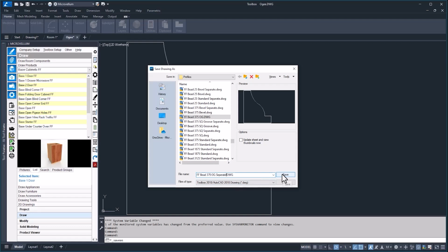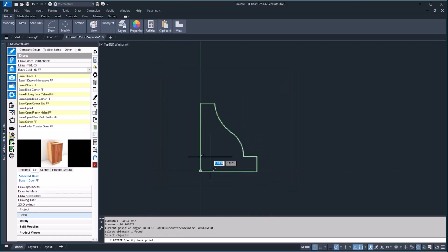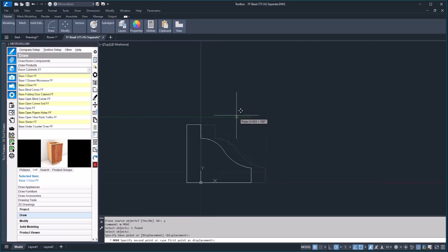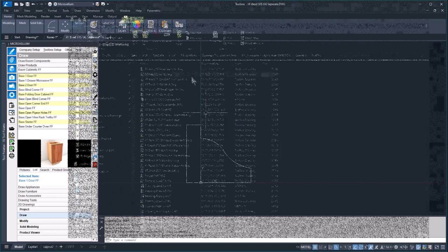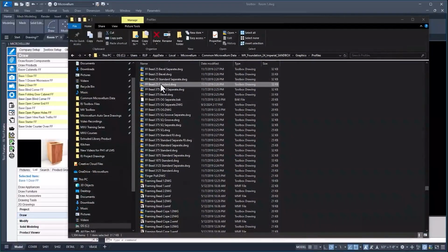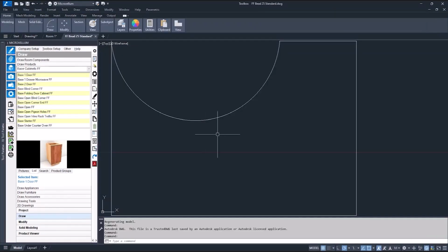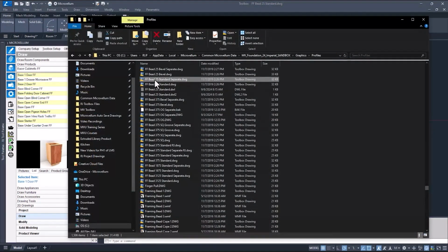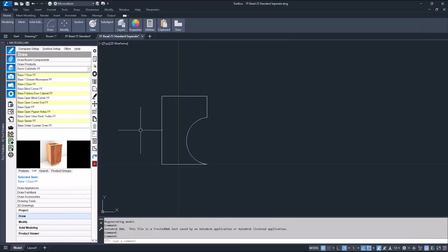And then before closing out of this drawing file, I'm going to need to rotate and mirror this object. And this is because of the way Toolbox references the drawing when adding it to the Microvellum product. Now, I only know this because I opened up some of the other drawings in the factory data and saw the differences and how it affected the product. When this drawing changes or the file is missing from the folder, it affects the Microvellum product.